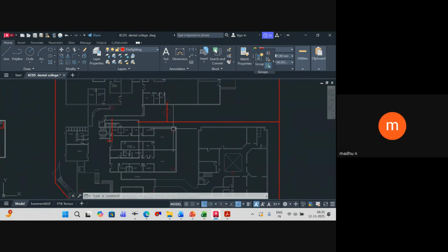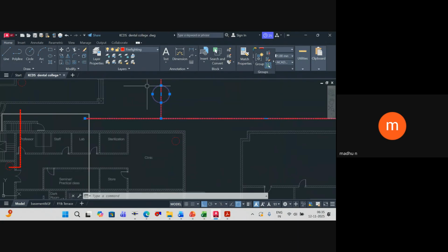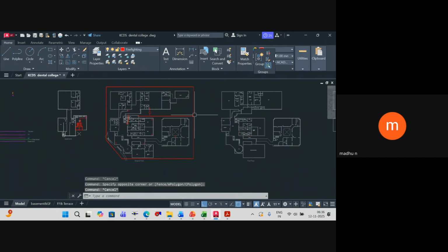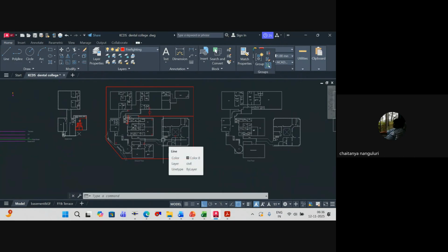Can we combine zones and put isolation in this one alarm valve? No, each zone should have its own alarm valve. Okay, now in this case we'll have 3 alarm valves. Yes. One for this, or I can even split it into one more also. Because instead of all the headache of taking the pipe throughout the rooms, it will be tough. Probably I can introduce one more zone as well, right?